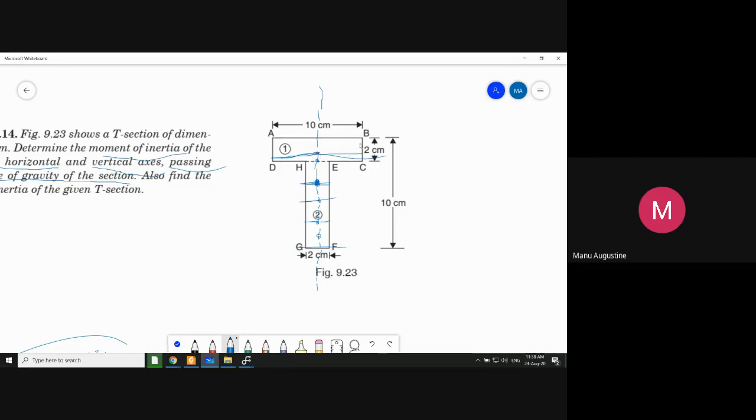So that means more area is available at the top side. तो इस कारण से मैं एक गेस ये लगा सकता हूं कि इस टी शेप का अगर टोटल हाइट 10 है, तो इसका सेंट्रॉइड 5 पे नहीं मिलेगा मुझे, 5 से थोड़ा ऊपर मिलेगा, क्योंकि ऊपर की तरफ भारी एरिया ज्यादा रखा हुआ है. So this is the logic I am using to approximately guess that the centroid will be somewhere around here. That means near to this upper part.